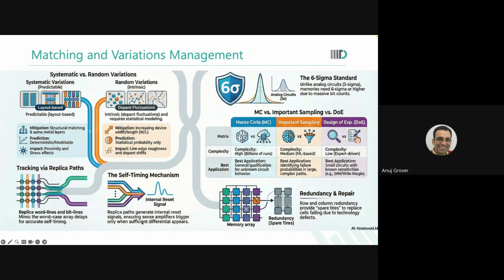Well, the sense enables will be the same for all these sense amplifiers. Yes, but there is RC delay coming in here. Is this magically traveling from here to there? No. There is an RC here. This RC can be hundreds of picoseconds.